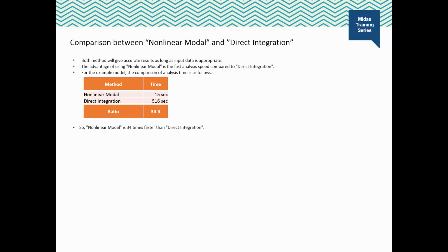With this slide, I will conclude my presentation. Summarizing the takeaways, I would mention that base isolators are effective in reducing the design seismic force and hence saving the cost of material. We have seen the various types of isolators and dampers available. For the analysis of such systems in 3D FEM software, the nonlinear modal superposition method is recommended over the direct integration method. Thank you.